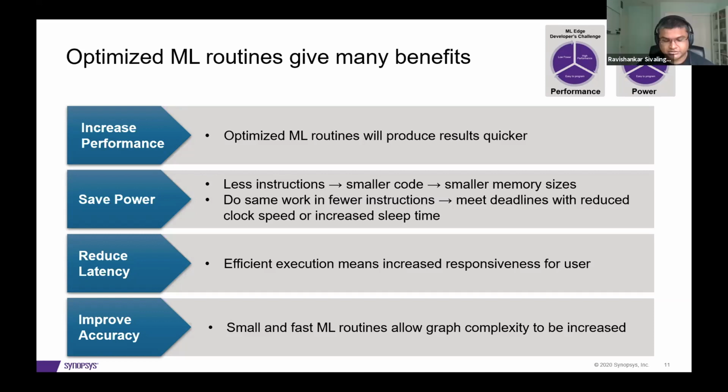Okay, just to follow up on that, I was going to ask about the size of the networks, like in terms of the weight memory that can fit in the memory that you talked about, the XY memory. Would that also depend on the kind of instantiation, like how they manufacture it? That's right. So the core is customizable. So you actually get a tool, if you license the RTL, that allows you to configure all things about the processor, including the sizes of the XY memory.